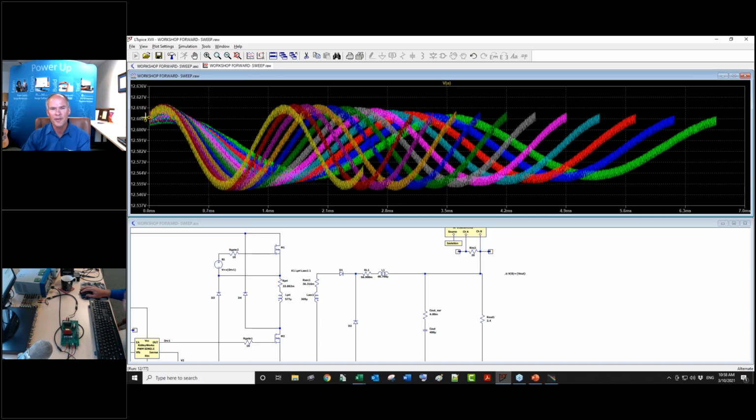So we're talking about 50, 60 millivolts on this signal versus 600 millivolts on that signal. At this point, we've got about 20 dB of gain in the system. And you can see the signal here is growing, because the loop gain is going up.